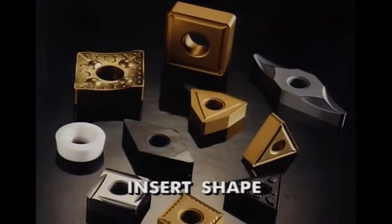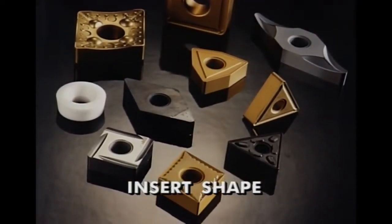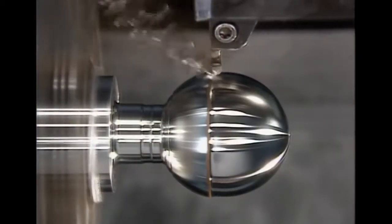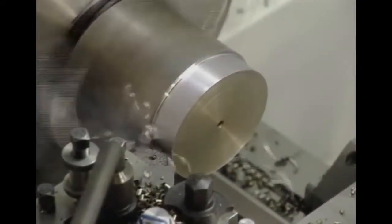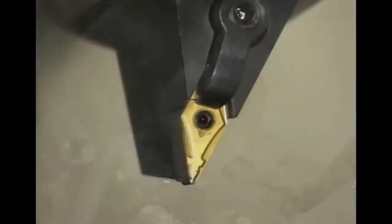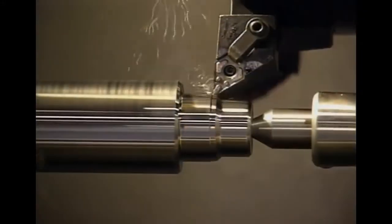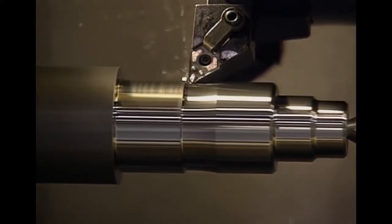For turning, insert shape selection is based on the trade-off between strength and versatility. The larger point angles are the strongest and most economical. Those include round inserts for contouring and square inserts for roughing and finishing. The smaller angles, such as the 35-degree diamond and the 55-degree diamond, provide the greatest versatility for intricate contouring.